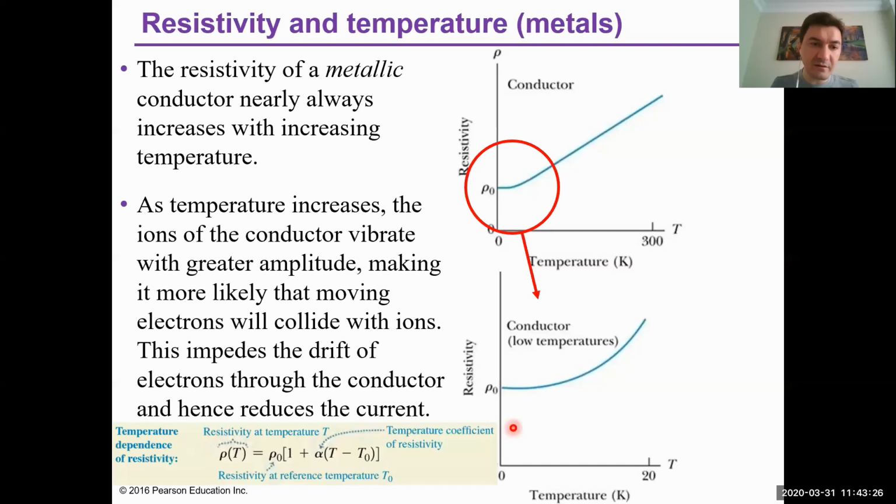So this resistivity versus temperature can be explained with that formula. This is resistivity at certain temperature. For example, you are looking for the resistivity at that temperature. So we need resistivity at certain temperature. So this is given by 1 plus alpha times temperature of that position minus temperature of this reference, okay? So what is this alpha?